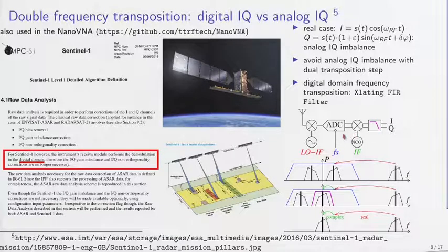The challenge of this IQ detector is that we assume that whatever signal is being mixed with the 2 copies of the I and Q signals are in quadrature. So the assumption is that this oscillator here feeds this mixer to create the I component, and the assumption that is being made is that the quadrature component is a copy of this oscillator shifted by 90 degrees.